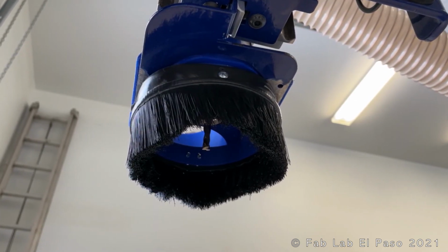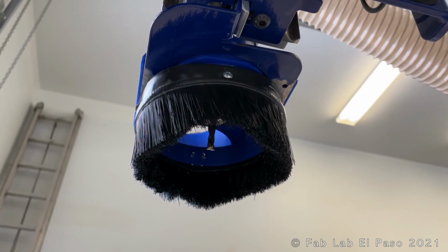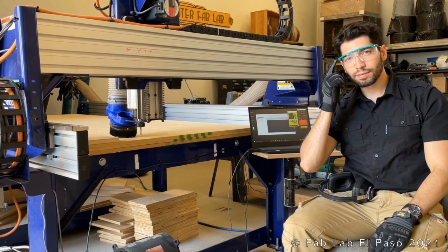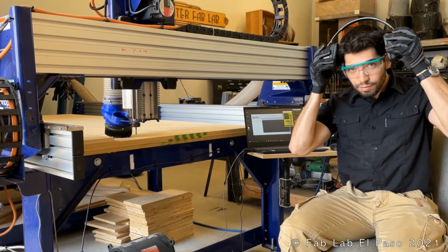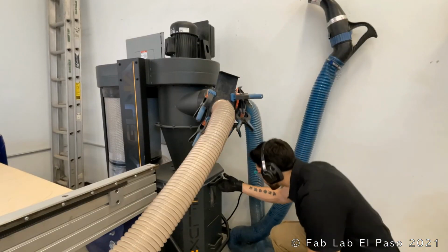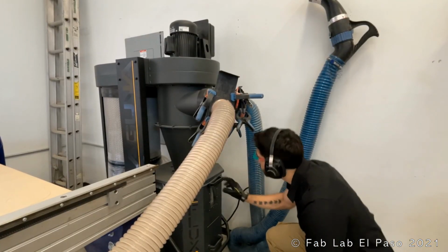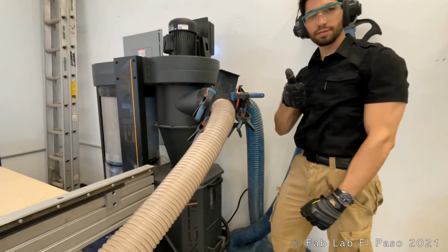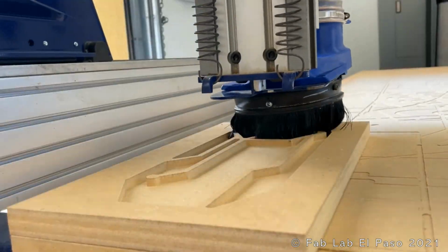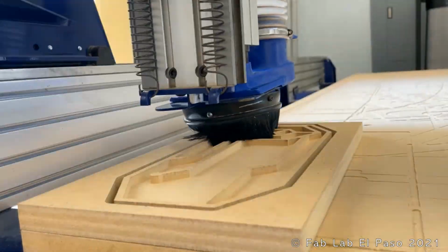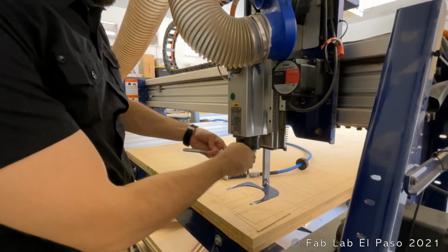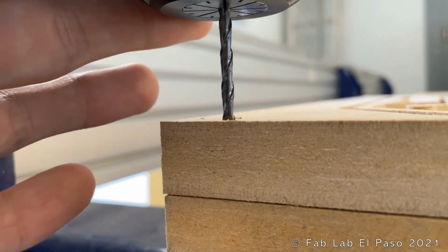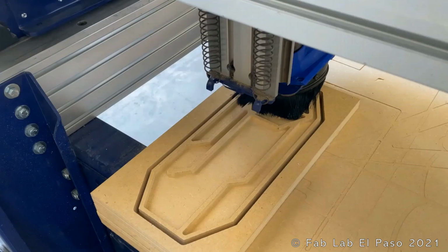Warm-up is finished. We have the right tool in the spindle, and of course, safety equipment on, which is safety glasses to protect our eyes, ear covers because it can get quite loud in here, and the vacuum clean and running so it cleans all the debris, preventing it from us inhaling that or making a mess or even starting a fire with the friction of the tool. We let it run, and once it's finished, we switch tools, re-zero only the Z-axis because X and Y must remain the same, and we select the next job and repeat.